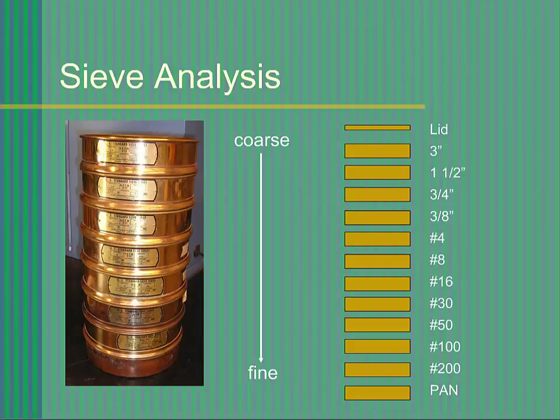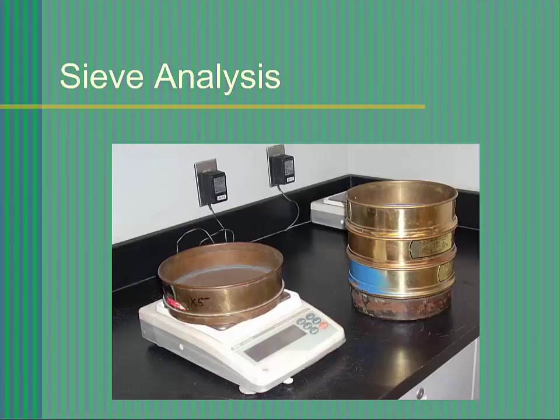You may not need all the sieves shown in this stack. The exact arrangement of sieves will depend on the nature of the soil you are testing. Once you have determined the sieves that will be in your sieve stack, clean each sieve to remove any loose soil in the sieve and measure the empty weight of each sieve.